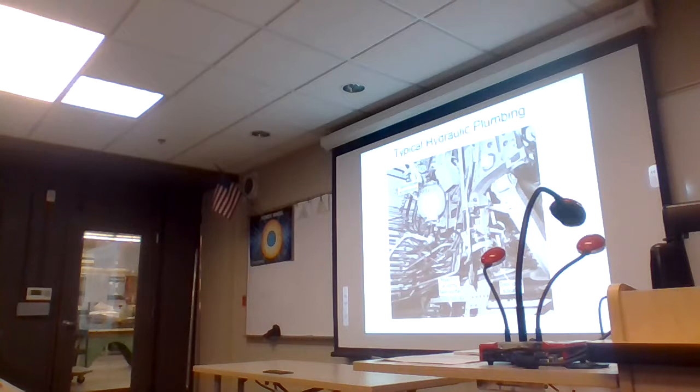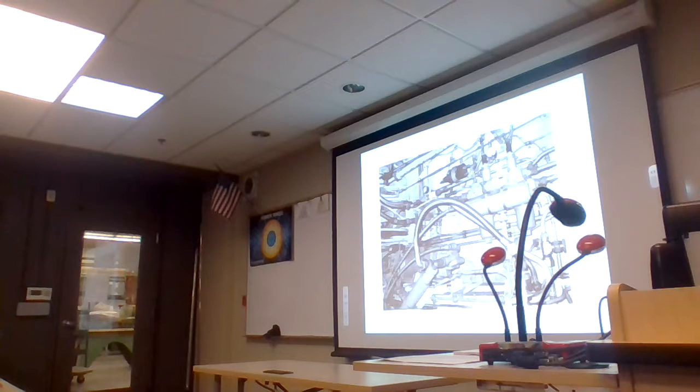This came from a Douglas aircraft, I think a DC-8 or a DC-9. But again, there's a brake accumulator inside of an aircraft, a door latch assembly, and the reservoir servicing hand pump. Some aircraft, in order to fill or replenish the reservoir quantity, have an onboard hand pump that they put into a container of hydraulic fluid and they replenish the reservoir with it. So it's an onboard piece of equipment that is already there.